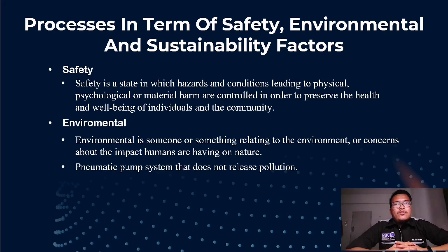The material of this project model is made from plain carbon steel. When we compare this material with other materials, this material is stronger. Carbon steel is an iron-carbon alloy which contains up to 2.1% carbon. For carbon steel, there is no minimum specified content of other alloying elements. However, the purpose of choosing plain carbon steel is that it has low corrosion and oxidation resistance.